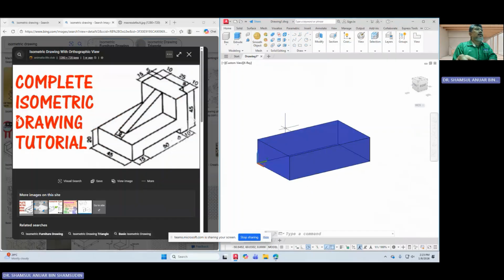So I can create another box here. I'd like to move my XY coordinate system, so I'm going to use UCS and put it over here, X pointing this way, Y pointing that way. And I want to create another box. I can go to red color and create the box.